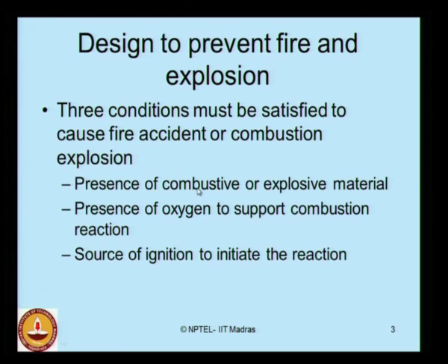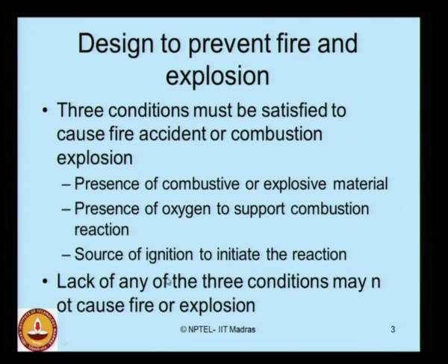Essentially, combustible or explosive material should be present. There should be presence of oxygen to support the combustion reaction, and of course you need a source of ignition to initiate the reaction. Lack of any of the three conditions mentioned above may not cause fire or explosion. On the other hand, if you want to effectively design a system which can prevent fire and explosion, either